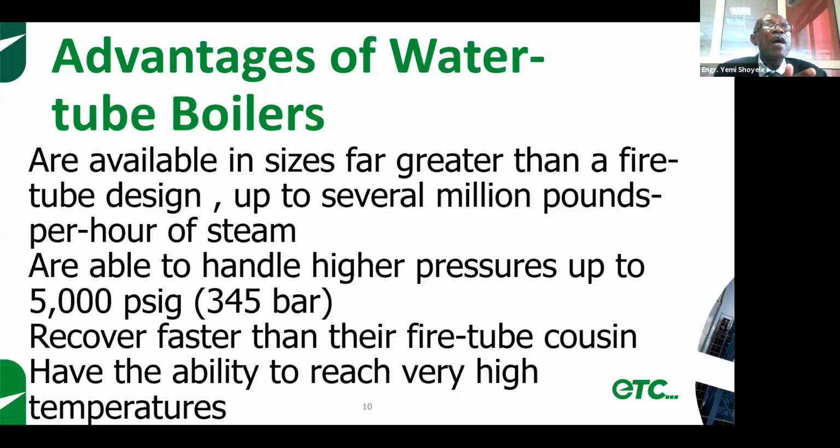For example, if you have a sudden demand of steam as a result of increase in load, or indeed, if there is a sudden drop in pressure as a result of a leakage or whatever, a big magnitude leakage, the water tube boiler will recover very fast because the water is in the tubes, and the tubes are relatively small compared to the fireplace. So the water gets heated up very quickly, as against the fire tube where the water is sitting down massively inside the shell. So it's easier to heat up and boil off faster the little quantity of water in the various tubes than to try to heat up water in the big shell of the fire tube boiler.